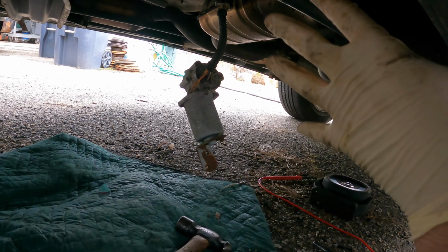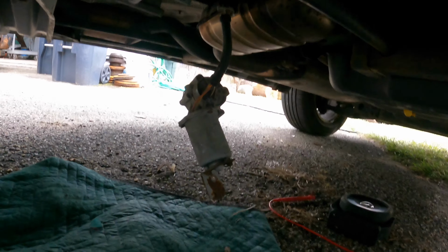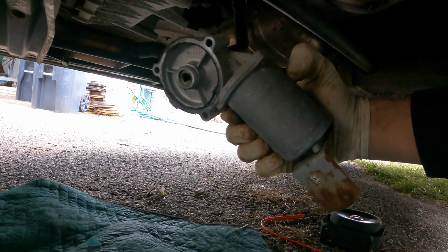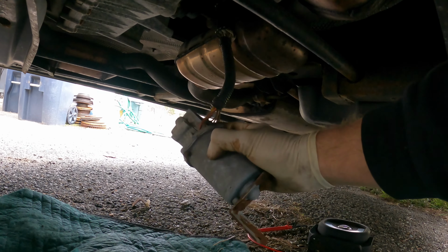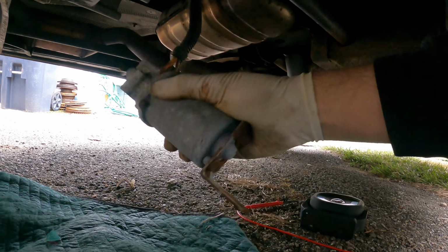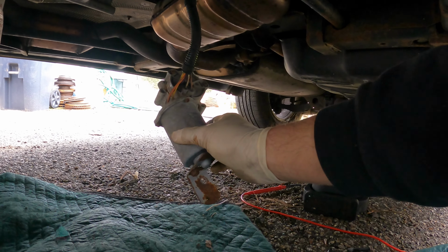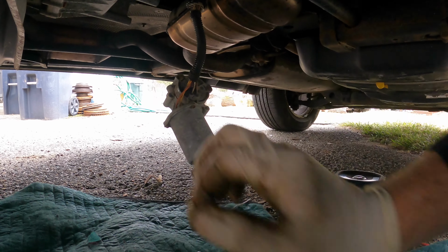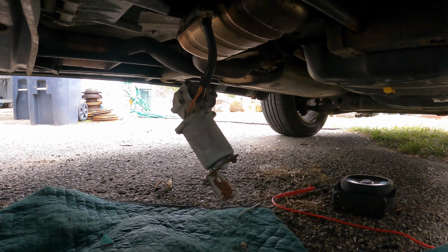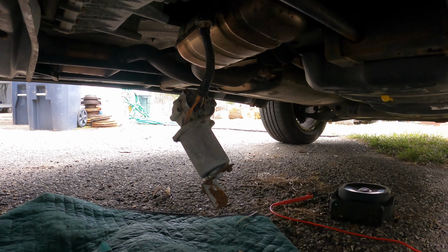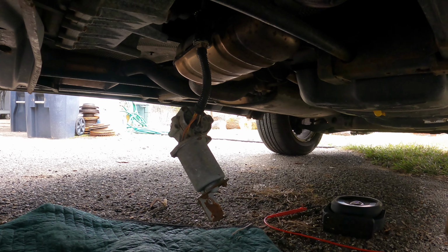Try tapping it, nothing is happening. So, the position sensor on these is inside the whole sensor. I think that's what our issue is. It doesn't know where it is, so it won't even try to activate. So I'm going to take this off. I'm going to remove the one from my other car. I'm going to swap it and we'll double check it again.